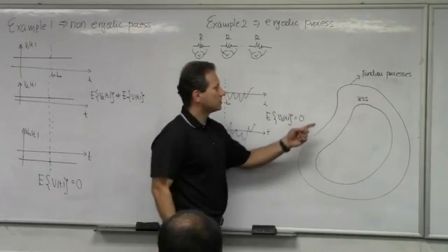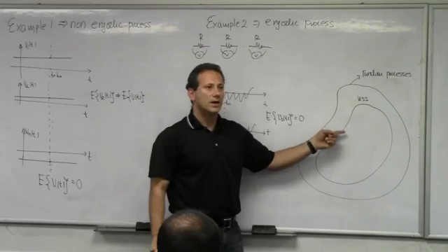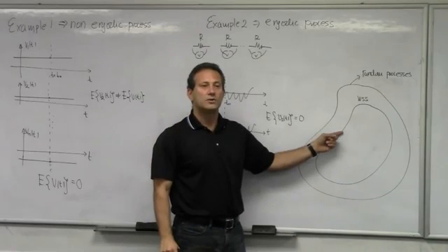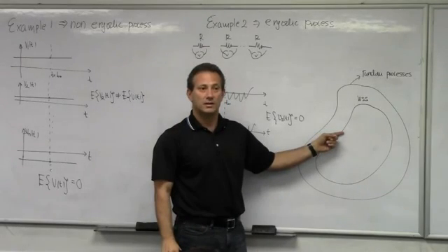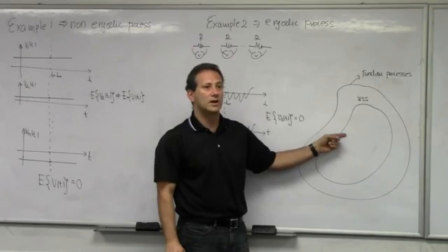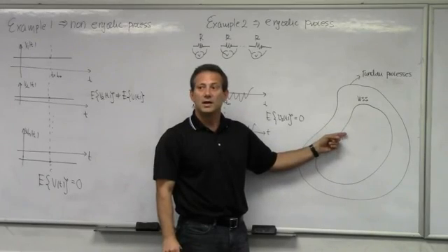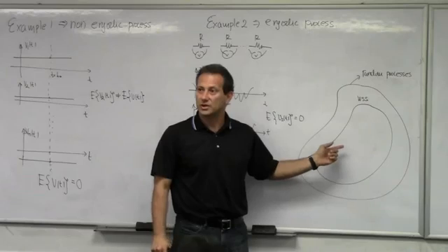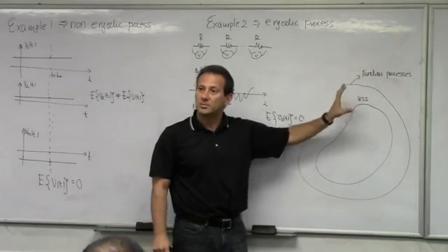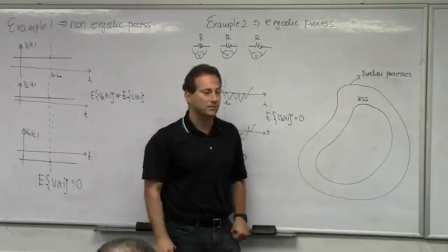How is the wide-sense stationary class defined? You have a process for which the first two moments in the amplitude domain don't change over time. The process has the same mean over time, the same power over time. The autocorrelation function does not change over time. If that's the case, the process is called wide-sense stationary.